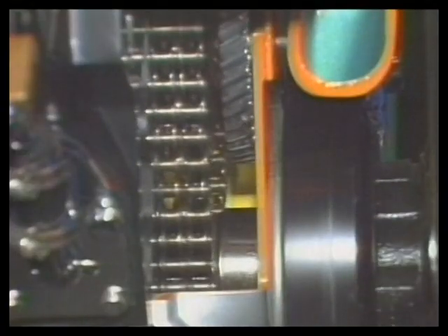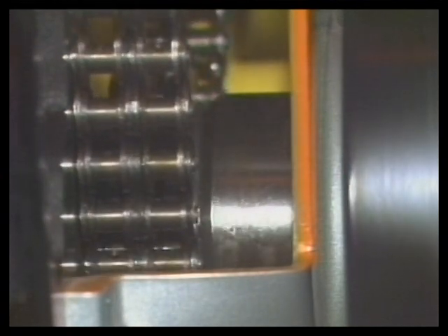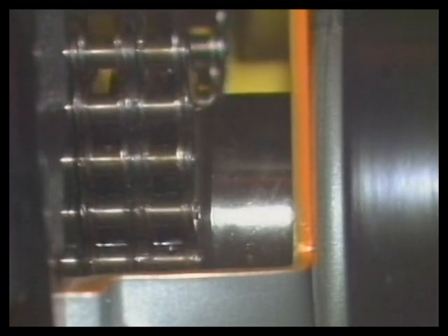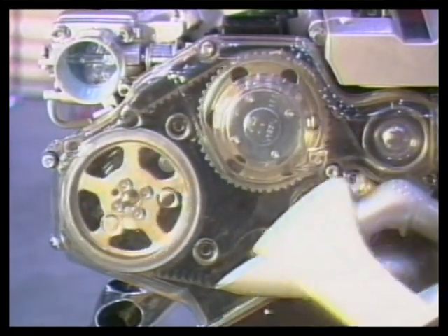The cam lobes are machined egg-shaped so that they can act upon the valves or valve train. For an engine to run properly, the cams must be timed with the crankshaft. Normally, the cam rotates at 1/2 crankshaft speed. Gears, a chain, or a timing belt are used to drive the camshaft or camshafts.